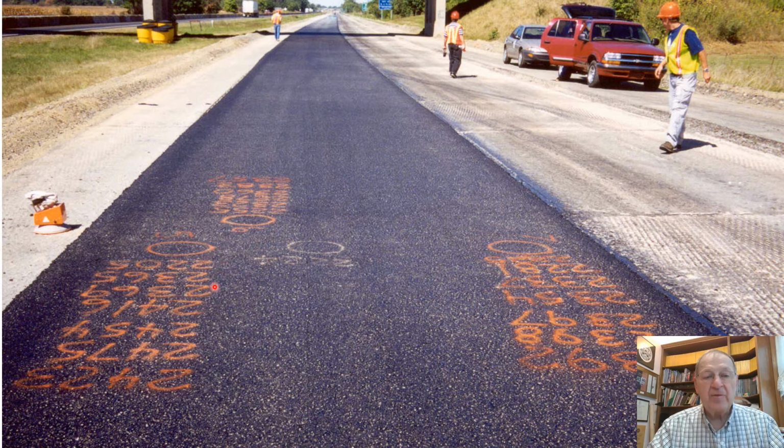What do we need? We need 2 breakdown passes and 3 intermediate passes, and then we're ready for finish rolling. So 5 passes. By slowing the roller down, we were able to accomplish passing density. Oh, I forgot to mention that the densities were about 1% higher than they had been back there where we used 14 passes.